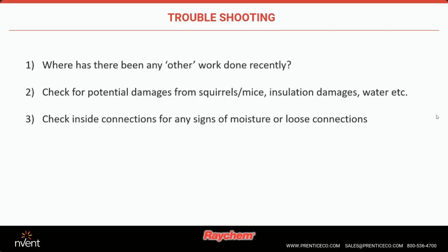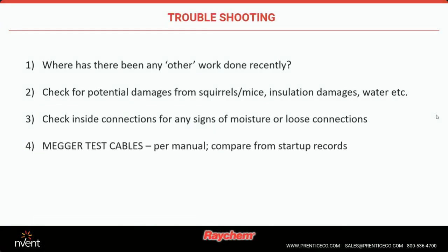So that's the first thing I always have them look at, other than the obvious first 2 points, looking at the connections first. Any signs of moisture, any loose connections inside of T's, power connections, end seals, any of those are going to be the first place that I'm going to tell you to start checking.